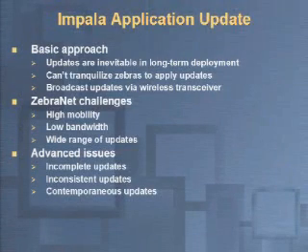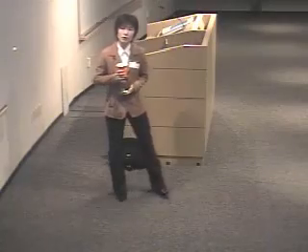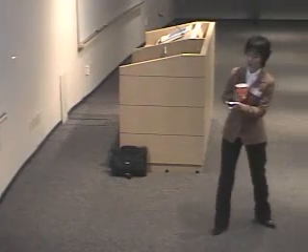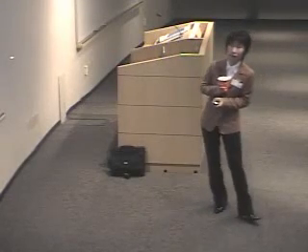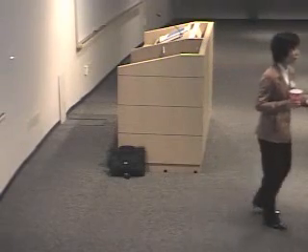So to answer this question, as I mentioned before, it is inevitable that software updates will be required over the lifetime of the sensor network. And we cannot tranquilize zebras for software updates. So the basic idea here is to broadcast updates wirelessly through the radio transceiver. For example, when the software updates first show up in the network carried by a sensor node, it will broadcast to all the network neighbors throughout the network until the entire network is reprogrammed.